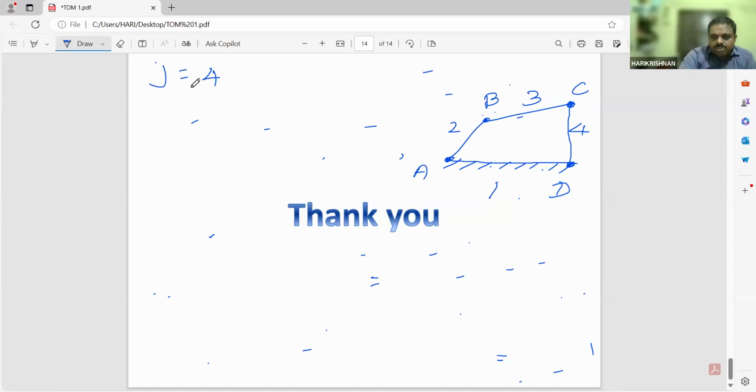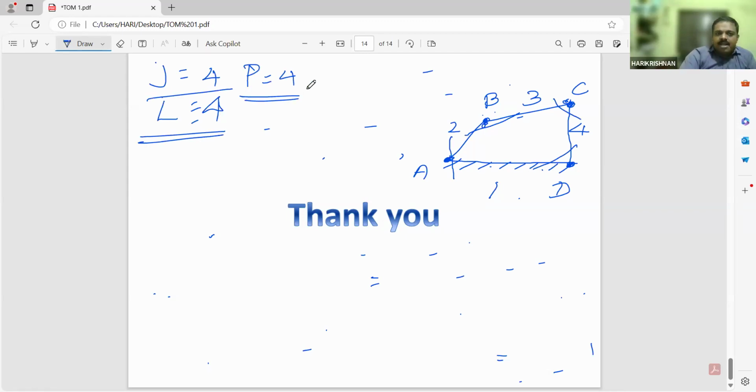J is the number of joints. A is one joint, B is another joint, C is another joint, and D is another. So the number of joints is 4. The number of links L is 1, 2, 3, 4. Now pairs: 1 and 2 will become the first pair, 2 and 3 the second pair, 3 and 4 the third pair, 4 and 1 the fourth pair. So the number of pairs is 4. The number of joints is 4, pairs is 4, links is 4.